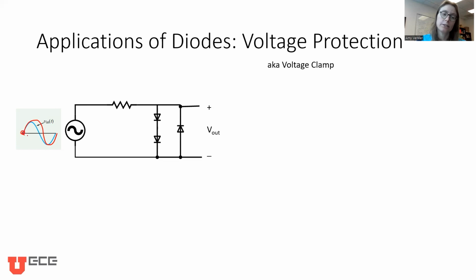But let's start here at 0 volts. So at 0 volts, none of the diodes are on, nothing's happening, the output's 0 volts. What about there around maybe 0.5 volts? Let's see what's happening then. If this is 0.5 volts, then that is not enough voltage to turn on both of these diodes in series. This one's facing the wrong direction, so none of them are on. So if none of them are on, there's nowhere in this picture right now for current to flow. So therefore, there's no voltage drop across this resistor, and therefore the voltage over here at this node is also 0.5 volts. We're considering this ground. So that means that in that case, V out is just equal to what V in is, the 0.5 volts.